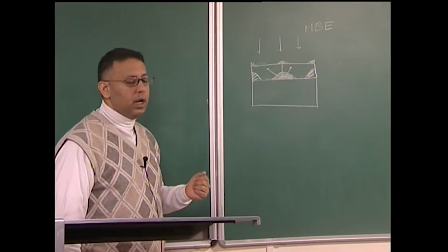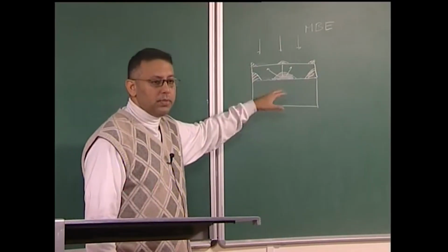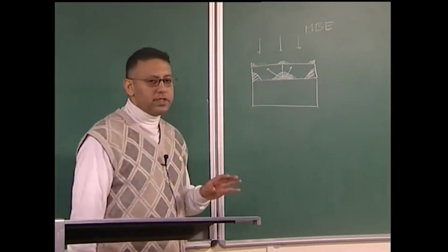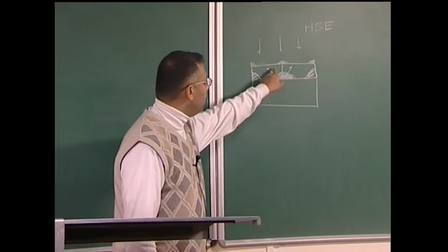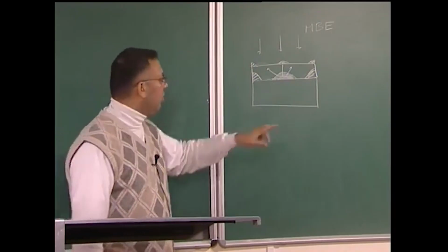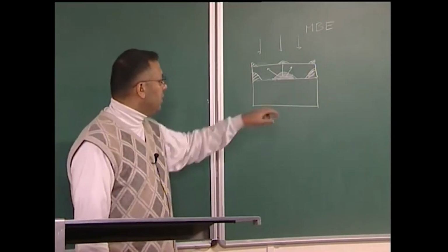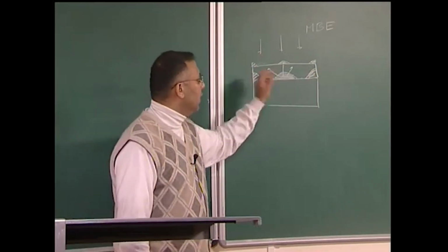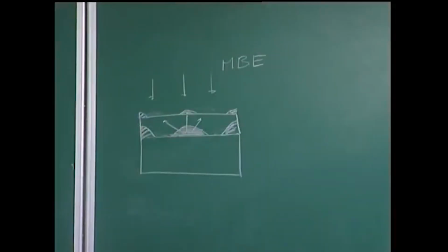So, in a case where there is no epitaxial system, that means for a glass substrate, then this kind of preferential alignment is not expected, unless of course again if there is some epitaxy between the overlayer and the film, or there is some other origin of residual stresses which can give rise to this kind of an alignment. Of course, this kind of an alignment can be preferred the larger the anisotropy of the system, in other words the overlayers which are grown on it.